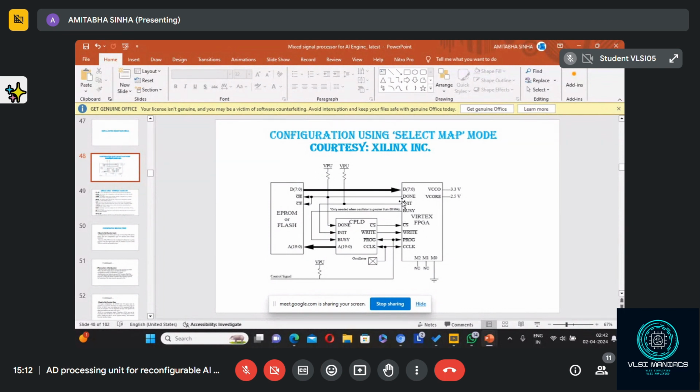Done means, okay, it has been done. When a particular operation is being performed, let's say download, the data is given to the data bus of the FPGA, then that data will be loaded and the write bar signal should be low. Any external device, when it puts write bar low, chip select bar low, and data in the data bus, will take some time to store this data, what is called the write time. Once that data loading, meaning writing, is complete, it will give a done signal. Understand?